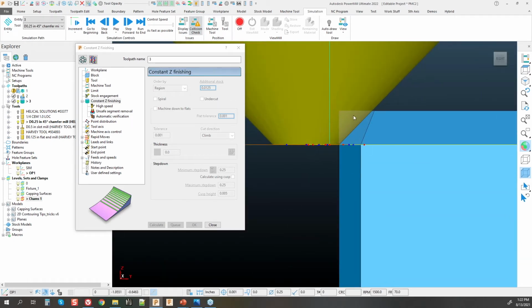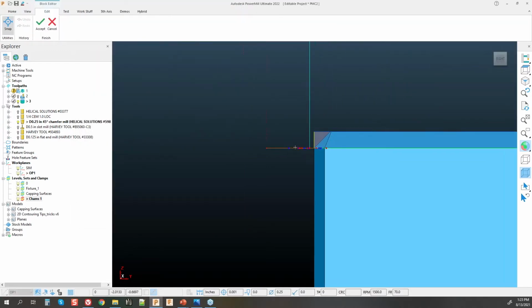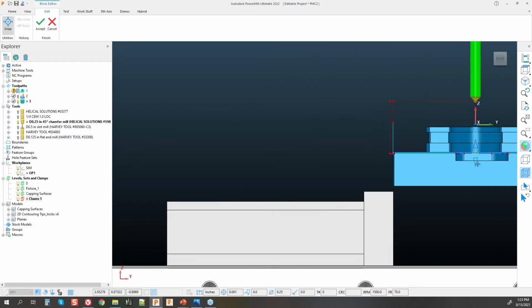Now, again, our block is kind of the master of our depth here within 3D toolpaths. So if I needed to adjust this and choke up on the cut versus being directly on the tip here, it's very easy for us to come in, edit the block after I've opened the settings, and adjust that down.